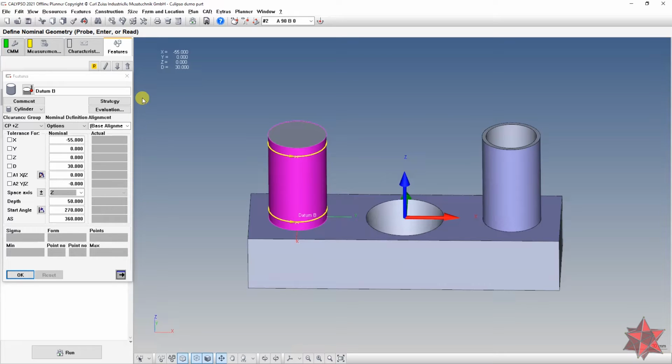Functional check is a quality process in which a part is checked against the designed function requirements. The check is for assembly purposes, prototyping, gauge replacement, incoming and outgoing inspection. The results will cover fitting and matching situations and functional datums, in order to accurately report the deviation of the workpiece.